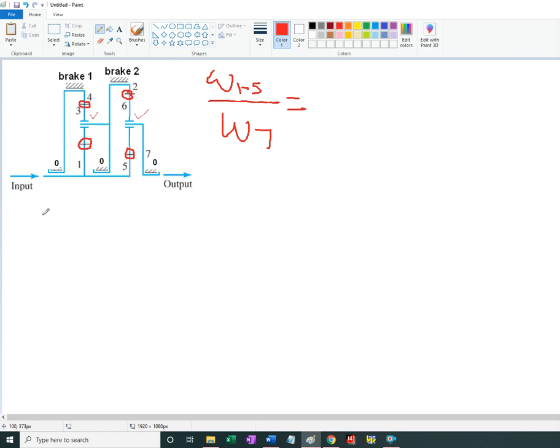For the first unit, I could write, not that it's the only equation, but overall only two are independent for this transmission. So I could write omega 1, and then again motion inversion, so I need to subtract omega of the carrier, which is omega 2, and going all the way to omega 4 minus omega 2.